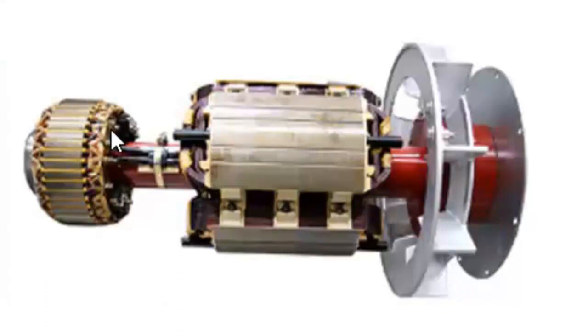At the back here, or at the front, I will show you later, we have the diode rectifier bridge. It is called the rectifier unit, and it converts the AC to DC before it is sent into the main field. So put that at the back of your mind: this armature produces a certain amount of voltage, which may be 12 or 24 or even 110.